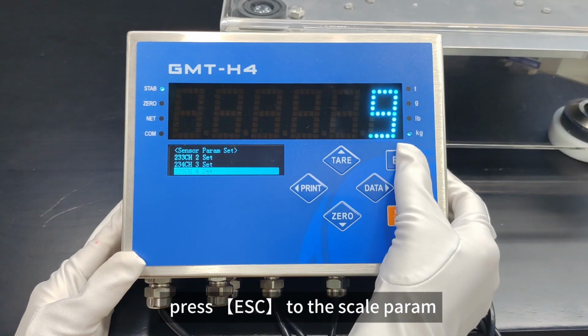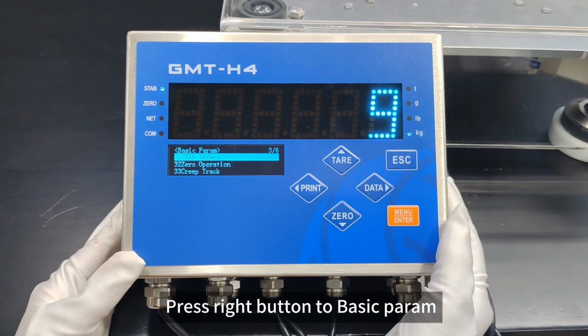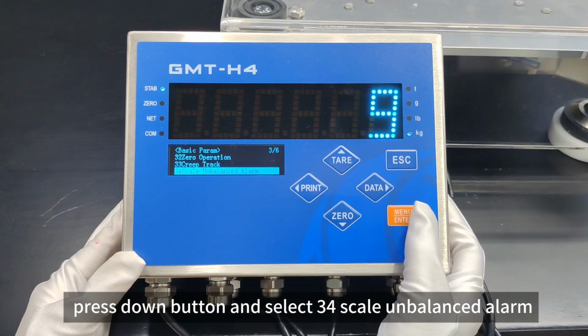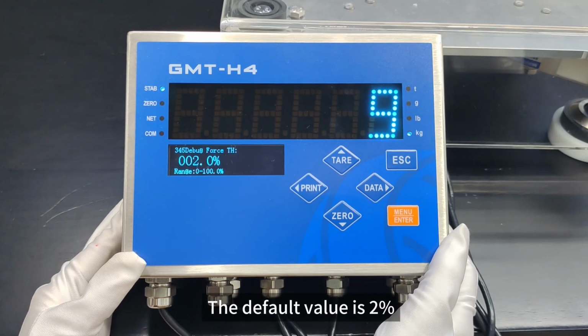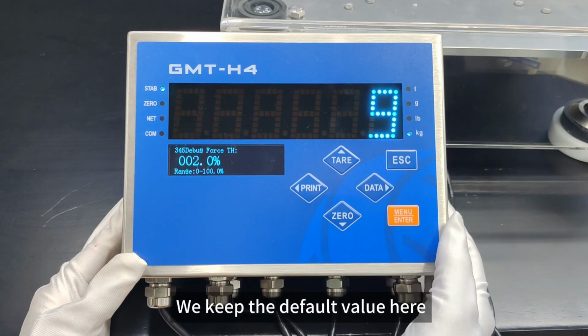Press ESC to the scale param. Press the right button to basic param. Press the down button and select 34 scale unbalanced alarm. Then press the down button to select force threshold. The default value is 2%. The value range is 0 to 100.0%. We keep the default value here.